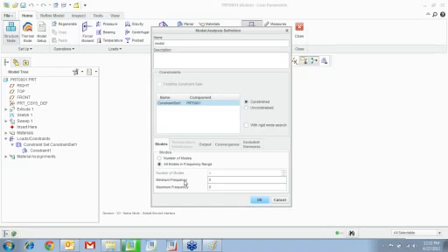You can also say, hey, you know what? This machine is going to be working on the bridge. The bridge's natural frequency lies between 500 and 10,000. Let me find out if there are any natural frequencies of this particular part within that range. So I can say, hey, find me natural frequency between 500 and 1000.